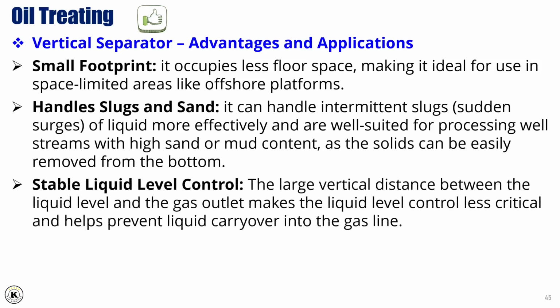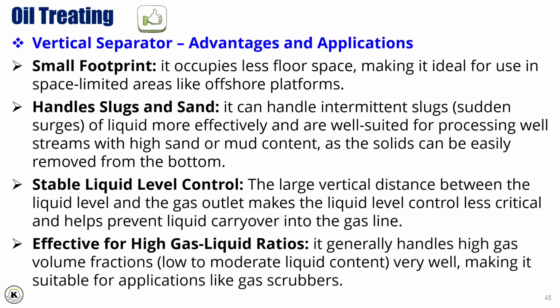Stable liquid level control. The large vertical distance between the liquid level and the gas outlet makes the liquid level control less critical and helps prevent liquid carryover into the gas line. Effective for high gas-liquid ratios. It generally handles high gas volume fractions, low to moderate liquid content, very well, making it suitable for applications like gas scrubbers.